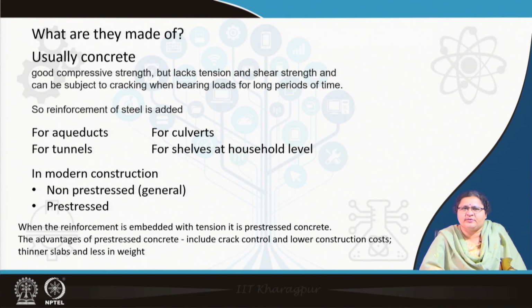We have the opportunity to use pre-stressed steel inside these precast items. Pre-stressed, as I told you, is when the reinforcement is embedded with tension in the rods. This is not possible in cast in situ construction. When it is cast in situ, you cannot pre-stress the rods.